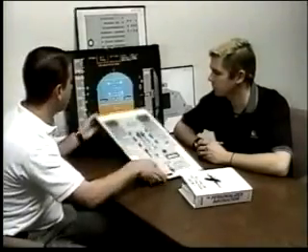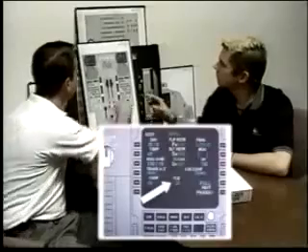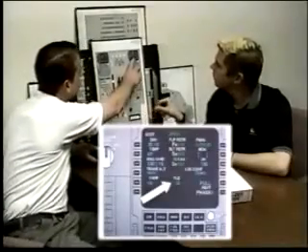Okay, if I come up to the FCU and I go select speed 100 knots, will the aircraft slow to that? No, the aircraft, with all the auto flights hooked up and everything, the aircraft will slow to VLS. If you're in alt or alt star, it could go below VLS, but for most cases, we'd be flying at VLS. The VLS that you find on your performance approach page on the MCDU, and it's in green.